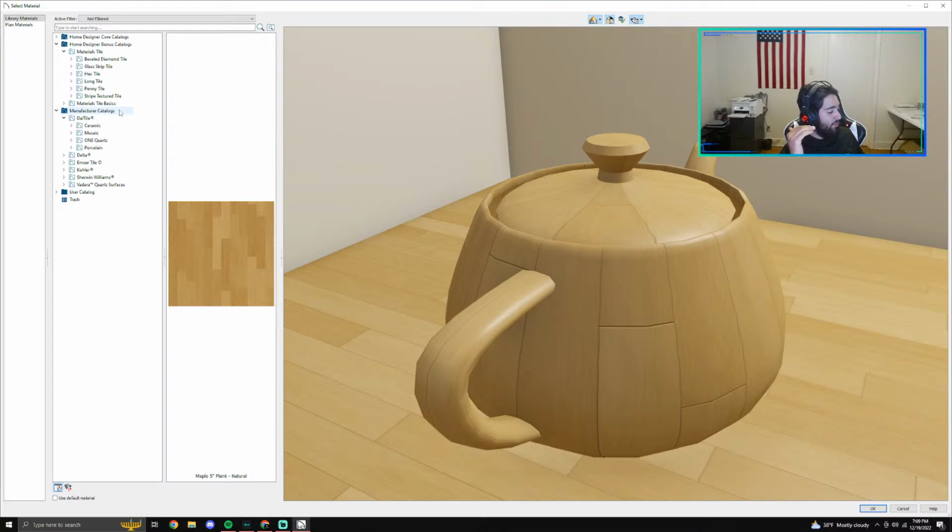So I have the floor tile, right? The floor tile in the shower is separate from the floor tile in the main area. I write all that information down, and then I have an Excel spreadsheet that I get pretty analytical with. I have 3 different packages that I offer. If you're more on the budget side, this is the lowest quality material and setting material I'm willing to use. Then I have my mid grade, and then I have my high grade for the floor tile. That's uncoupling membrane, and at the very minimum Trilite or 254 Platinum and everything.